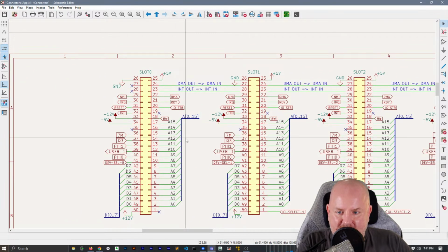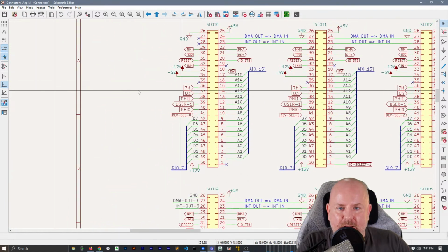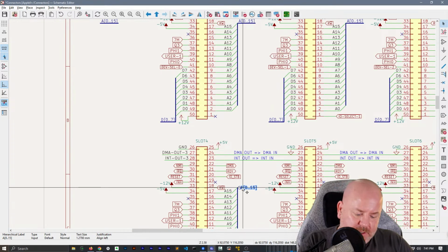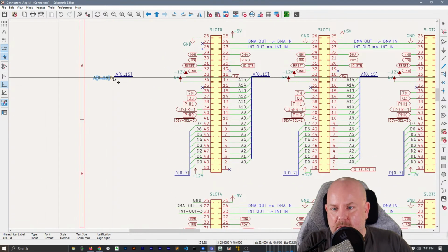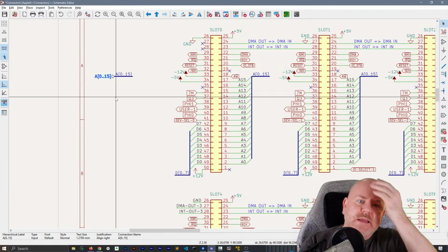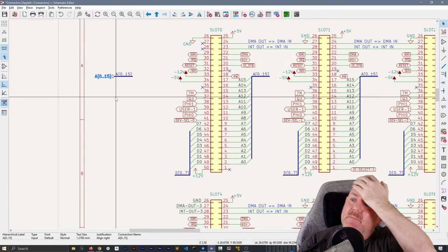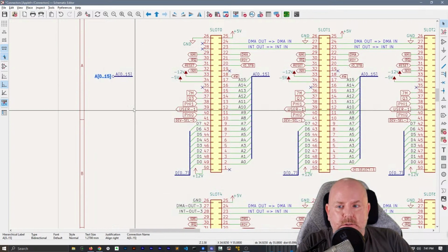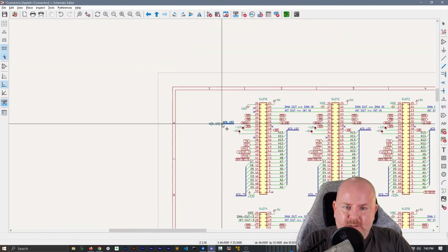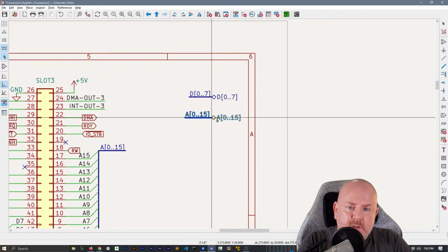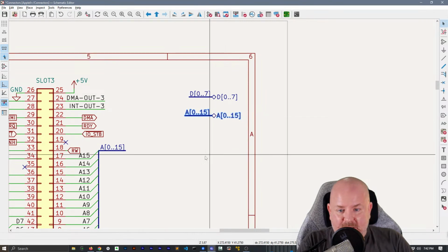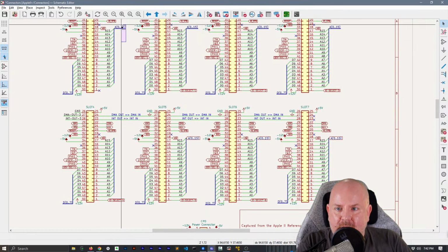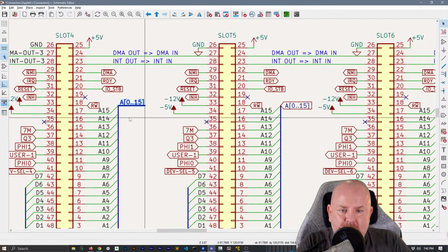It's just a shame this wasn't done in the... Oh, I meant to... Okay, I'll borrow that one. So what I want to do is convert this one. We're going to move that up here. Because the... Oh, wait. Slots, the address is bidirectional, because the slots can drive the address bus. It's normally single direction, but if they yank DMA down, then they can drive the address bus.